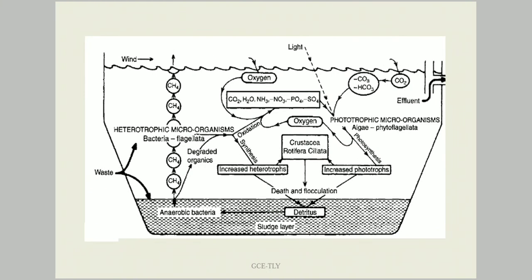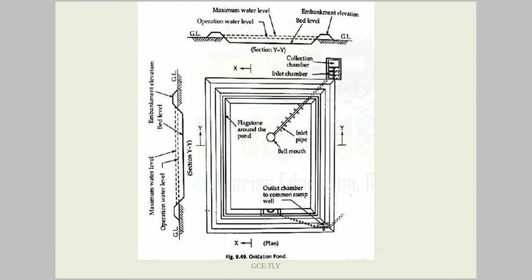Here you can see that at the topmost there is the aerobic process, while at the bottommost there is the anaerobic process. In the middle area, both aerobic and anaerobic processes take place together. This is the sectional view of an oxidation pond which is under construction.